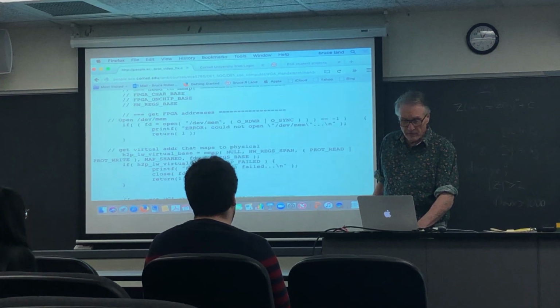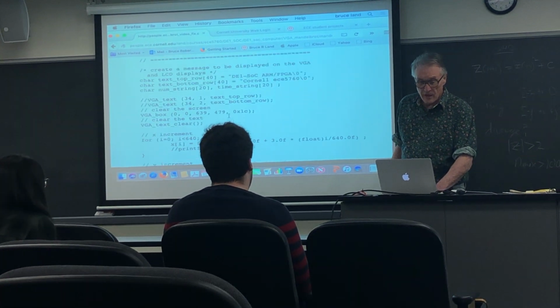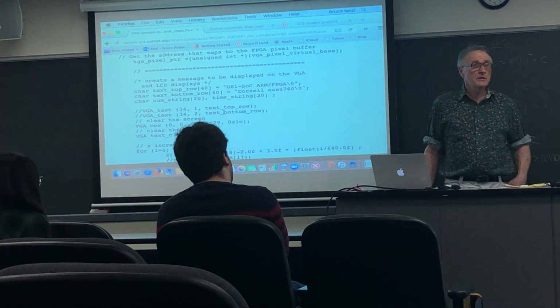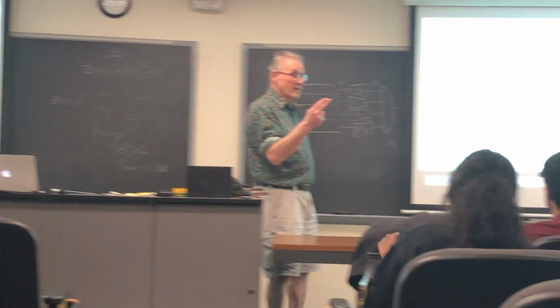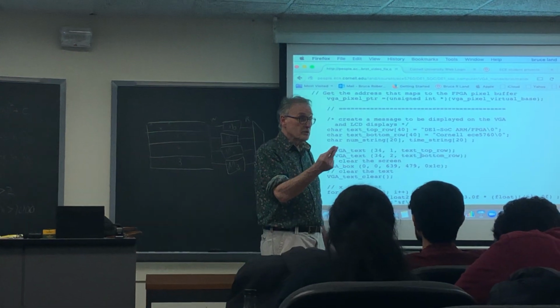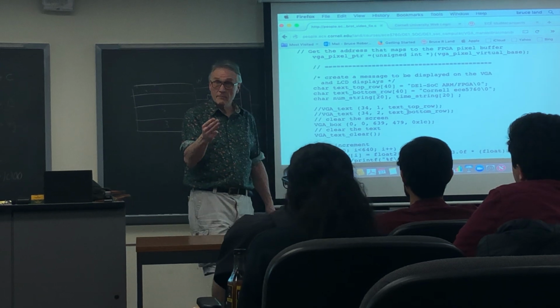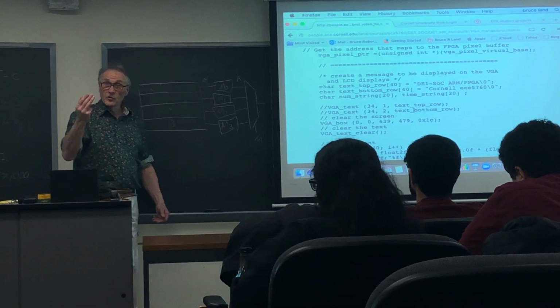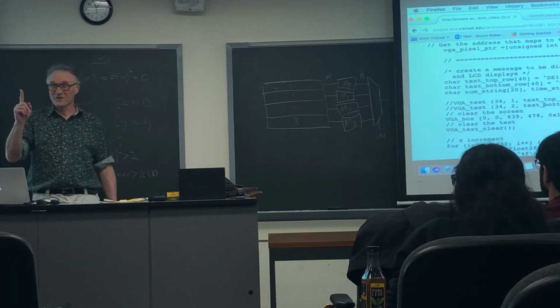And I believe that the reason is, although I'm certainly willing to be called wrong on this, that the ARM core we're using, ARM v7 core, is a limited dual issue core. It has dual issue on the integer unit, but not on the floating point unit. So you get 2 fixed point instructions on every clock cycle, but only 1 floating point instruction.